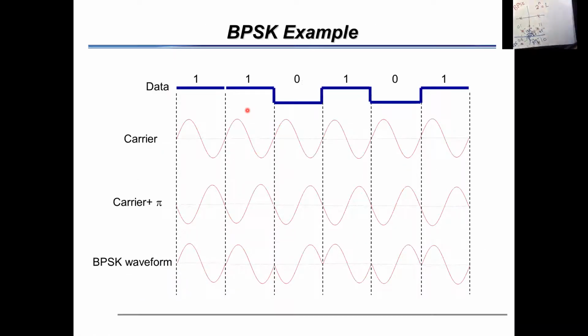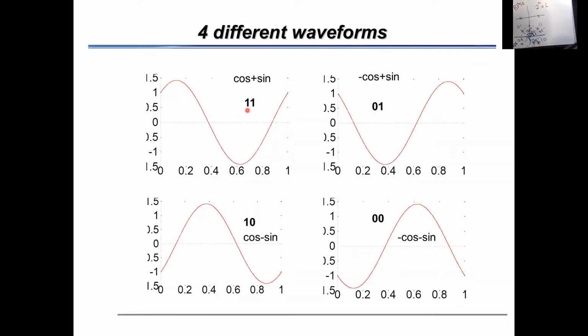in the TS, which is, for example, 1 second, you are transmitting 1 bit. So your data rate is 1 bit per second. However, here, you are transmitting 2 bits in a second. So you have a double data rate with respect to the BPSK. So this is the main advantage of the quadrature phase shift keying over the binary phase shift keying.